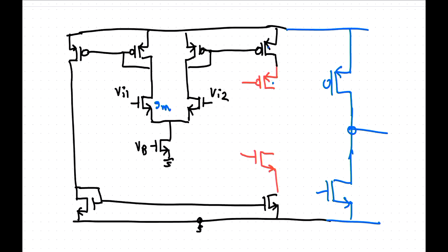So one way that you can bias it is by putting in a couple of transistors, because it's a very neat circuit here. So you put in 2 transistors like that, and you bias it like that. So that's VB1 and VB2 here. So in terms of what happens from the current source side here, you don't really change the impedance level in this node here.